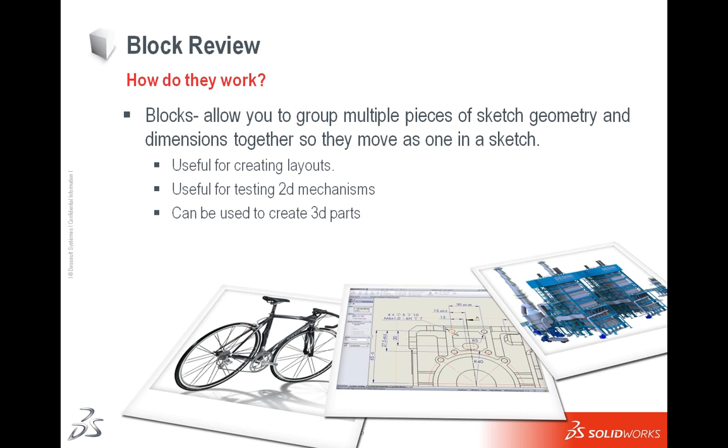Okay, just a little bit of block review before I go in. I'm going to actually create a couple blocks here. A block allows you to create multiple pieces of sketch geometry and dimensions so they move as one sketch. Fantastic for layouts. Very nice for testing 2D mechanisms, which I'm going to show a lot of in this webinar today. And again, we can use these to create 3D parts.